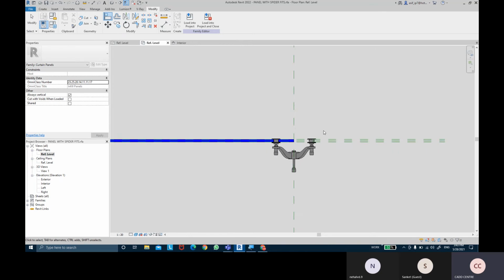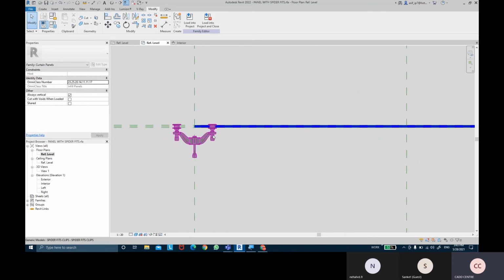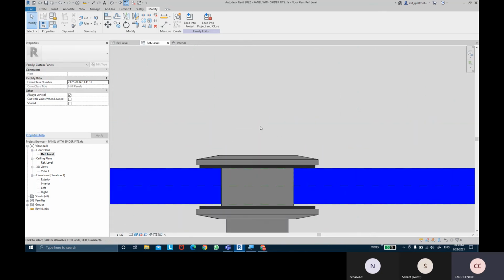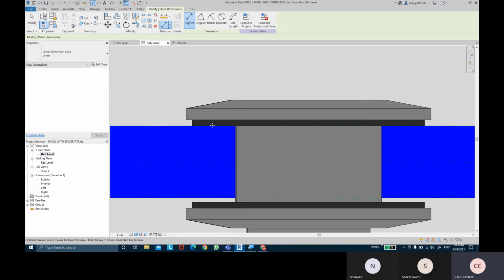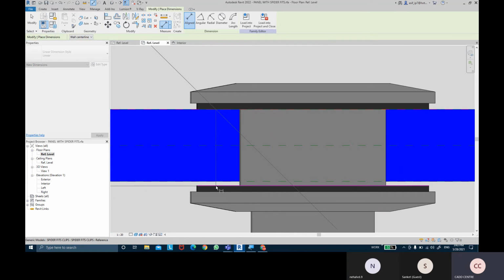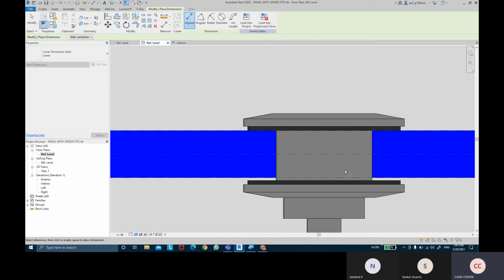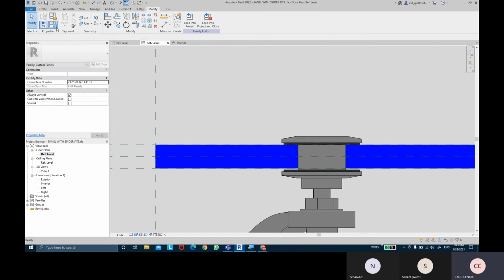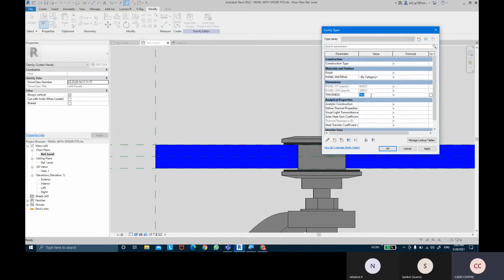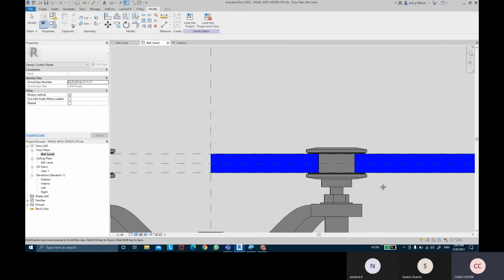So now that's it. Perfect. The clips go inside that element. Now the glass thickness is varying, which you can match. The glass thickness needs to be at least 19 mm to fit perfectly onto that. So we can set this glass thickness to 19 mm. Perfect, it fits.